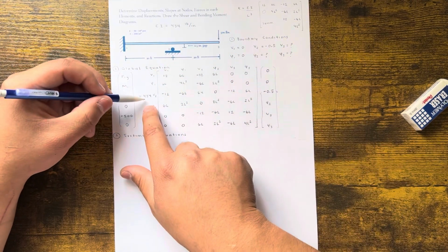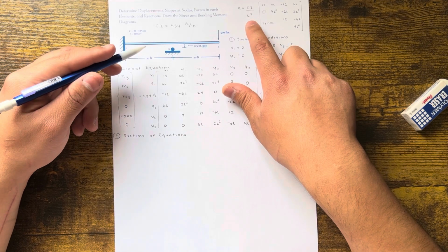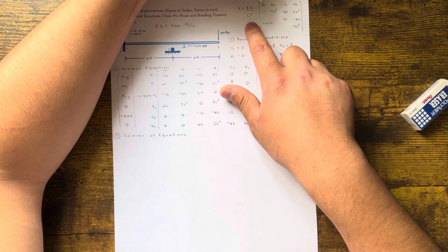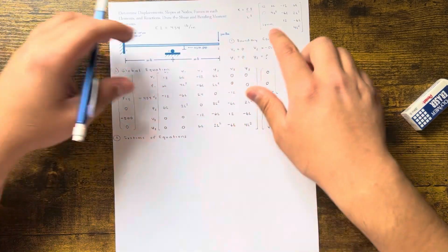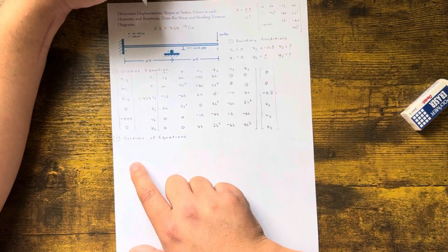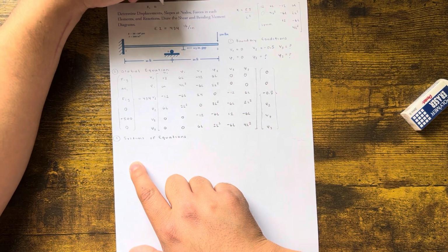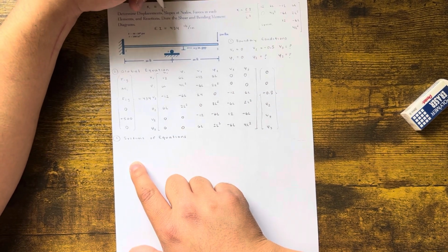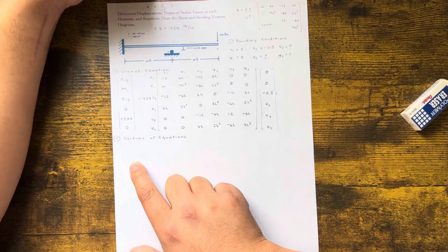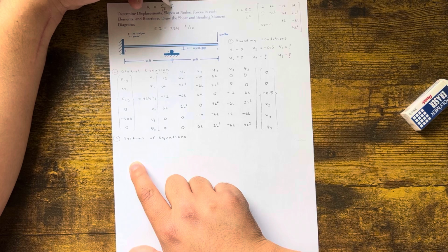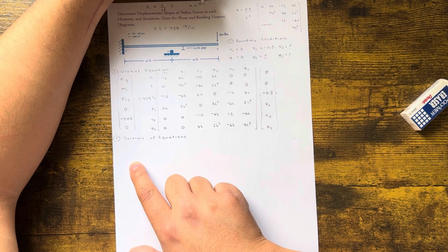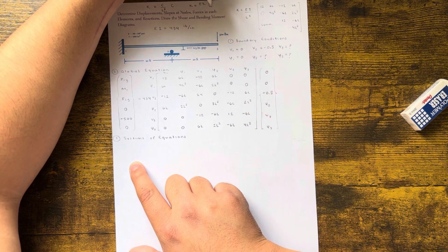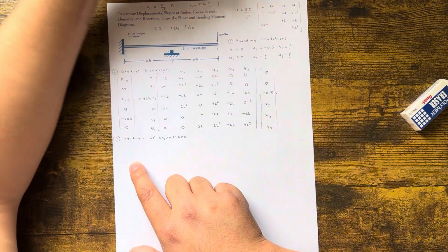And earlier when I said L cubed, when you have different size elements, you'll want to throw it in there. So 12 divided by, actually, hold on. Yeah, so in this case, if you know L, but it could vary between every element, so you'll probably have to throw this in sometimes. This is just K is equal to a constant over L cubed times, let's just assume another constant, right? So you can either divide this constant by L cubed or this one by L cubed. So if K is equal to, in this case, EI times all your matrix, you have to divide everything in the matrix by L cubed, if that makes sense.